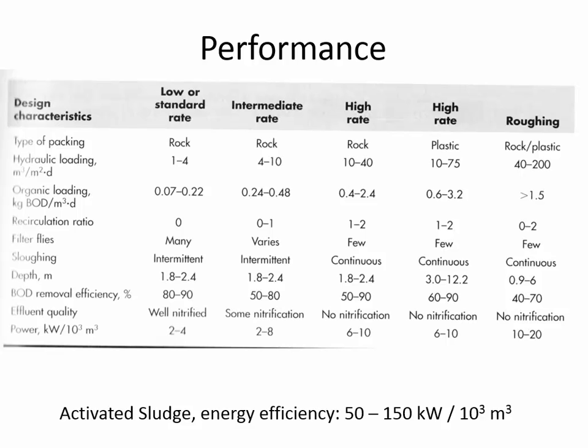And if you look at the removal efficiency, it has the worst performance of all the different columns. It's saying between 40 to 70% removal. Now that's nothing to sneeze at. If you can get half of your BOD removed using a filter that uses, in some cases, almost no electricity, then that's definitely worth doing.